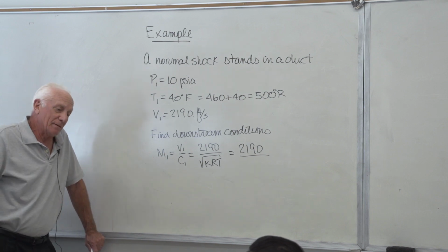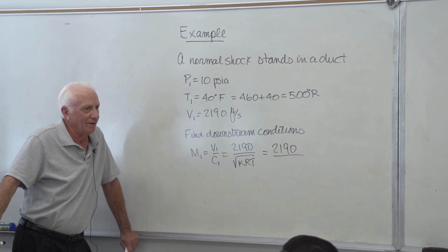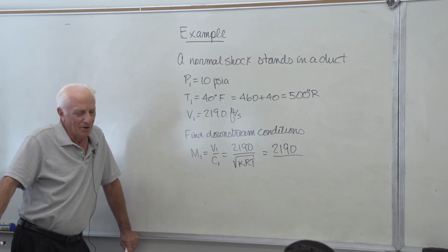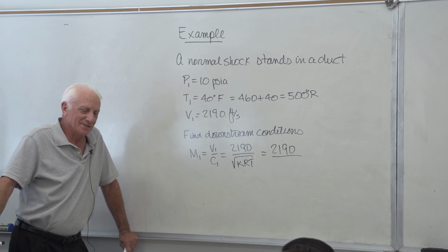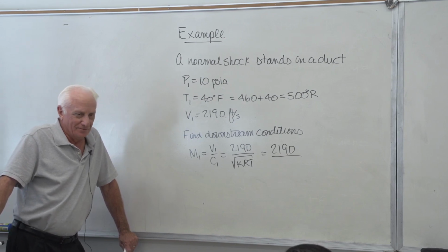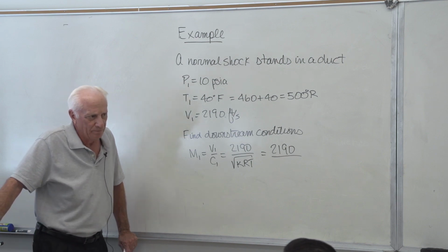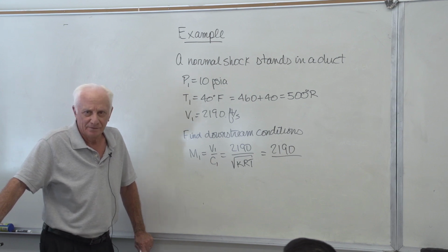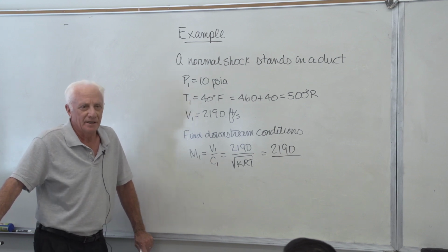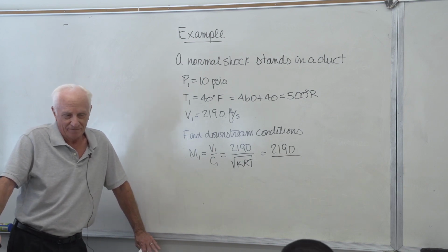We know in fluids, you've got to be very specific. You don't just say the pressure is 10 PSI. No, that's not good enough. I don't know what you mean. Do you mean gauge or absolute? You can ask the guy at Jiffy Lube, make sure my tires are up 32 PSIA. The guy says, pardon me, did you say 32 PSIA? I said, yeah. I said, what does that mean? Oh, I'm sorry, just 32 PSI is okay. See, we speak different language. We have to be very specific.